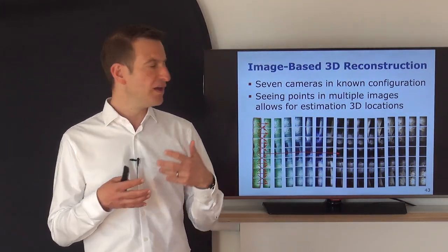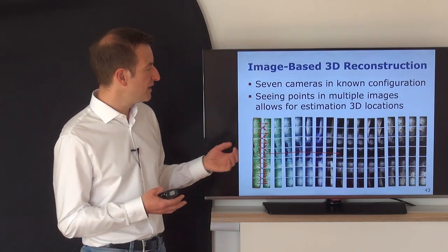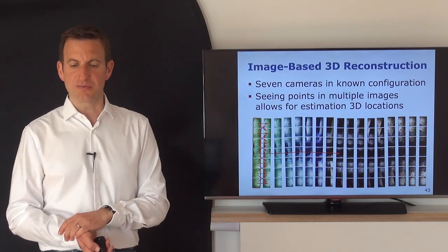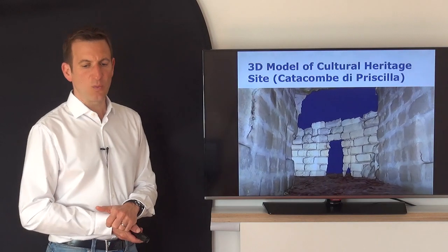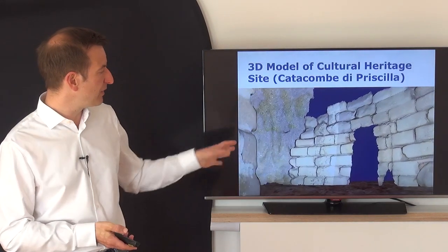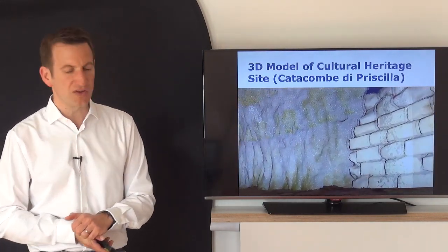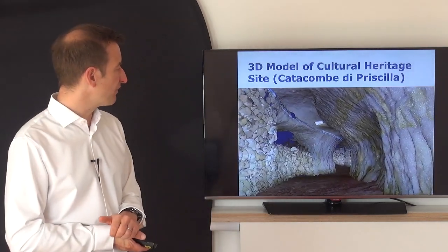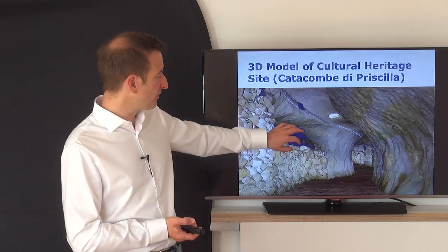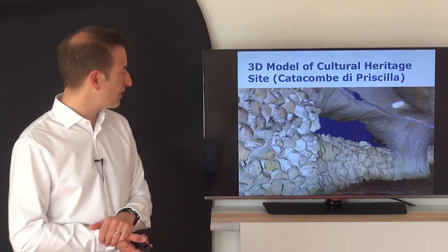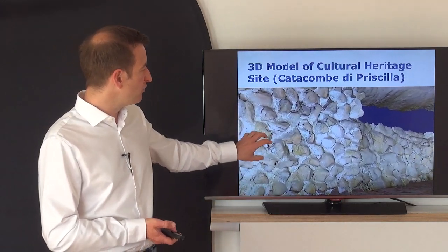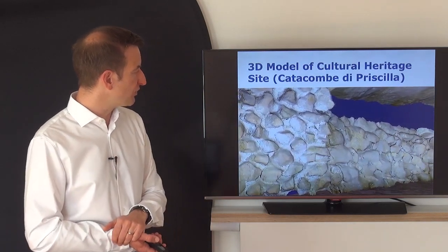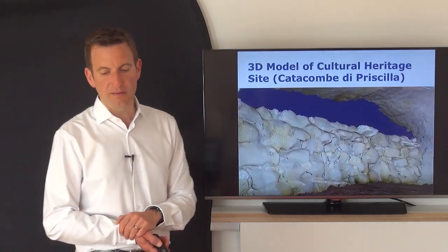And you can use these 3D locations that we are estimating to do 3D reconstructions, so that in the end we can obtain 3D reconstructions just from these camera images which look like this. So these are photorealistic reconstructions of the scene. The blue thing stems from occlusions because the robot was driving very close to the ground, but you can do high-resolution 3D reconstructions of the environment using this technology.